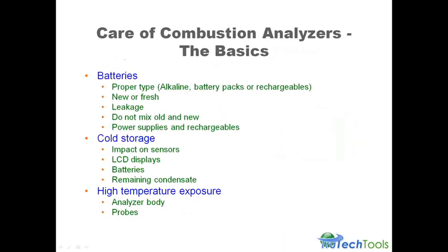Use new batteries. Cold storage: if you keep the analyzer in your truck all the time, I'd keep it in the front of the cab, under the seat or something, where it's going to get some heat from the cab, because cold does have an impact on the sensors. They're chemical sensors, so they slow down.